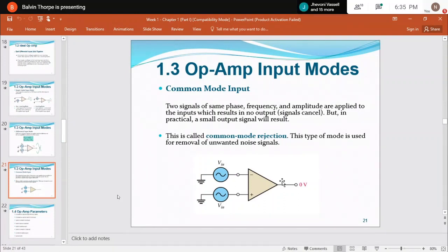So what you find is that if the common mode gain and the differential mode gain are closer for one transistor, as compared to another transistor where the CMRR is big, then it means that the second transistor with the big CMRR is performing better than the one with the smaller CMRR, because it is rejecting signals that are common and amplifying signals that are different at the input better than the first transistor.